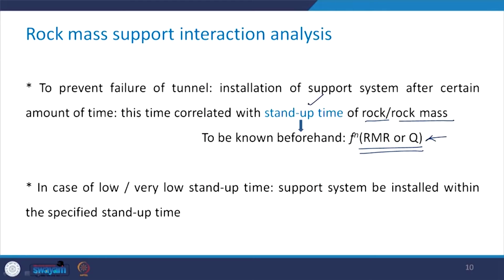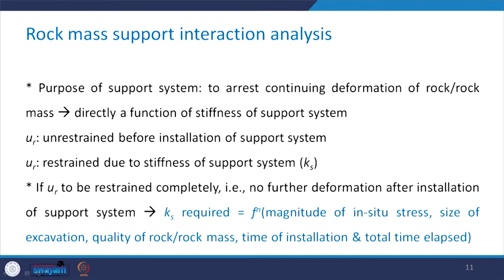Now, in case of low or very low values of the stand up time, the support system need to be installed within the specified stand up time. Now, what is the purpose of the support system? Is to arrest the continuing deformation of rock or rock mass, and therefore, this is directly a function of the stiffness of the support system.